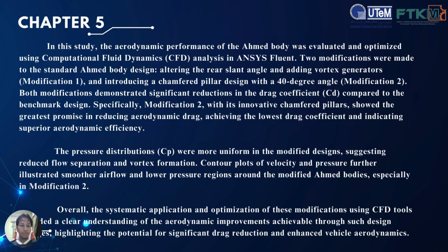The pressure distributions were more uniform in the modified designs, suggesting reduced flow separation and vortex formation. Contour plots of velocity and pressure further illustrate smoother airflow and lower pressure regions around the modified HAMID bodies, especially in modification 2.